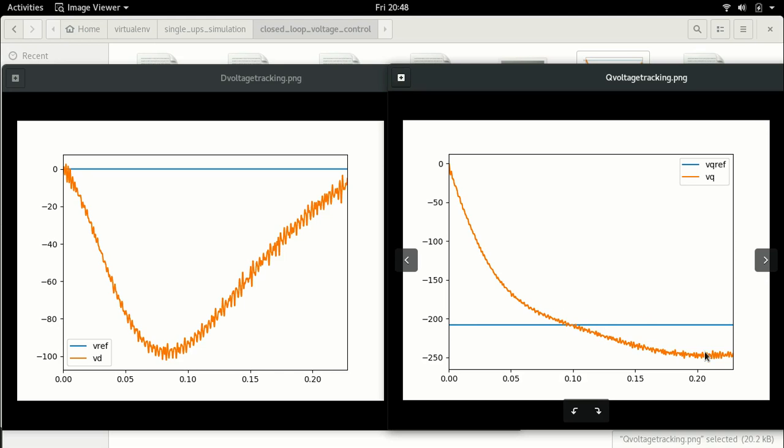The reason for this is simple: too much integrator or too little proportional gain. So there's two ways to go about it. One, you could try to increase your proportional gain and see whether this becomes a little better, or you could decrease your integrator and see whether this becomes better. Either way, control tuning takes some time. So the important fact is this is working.